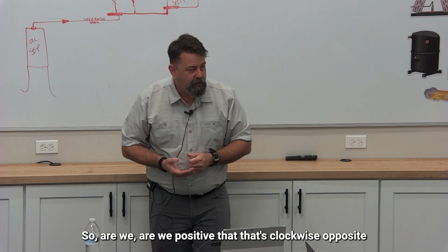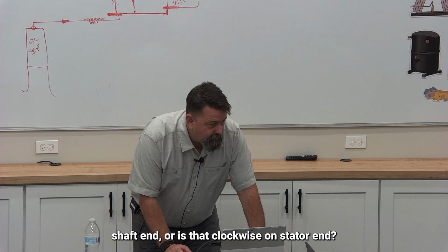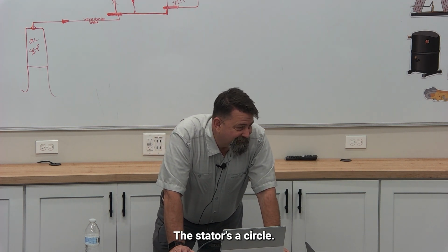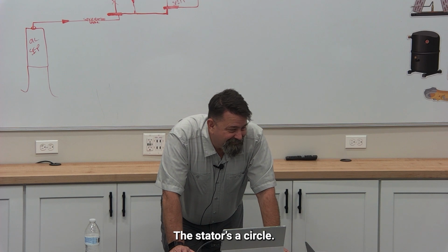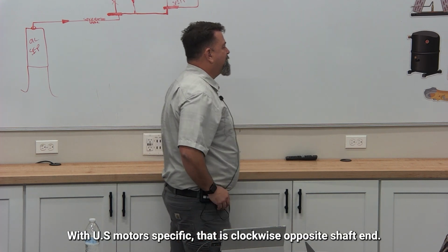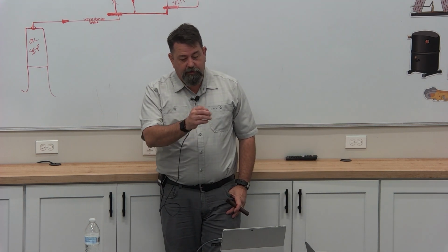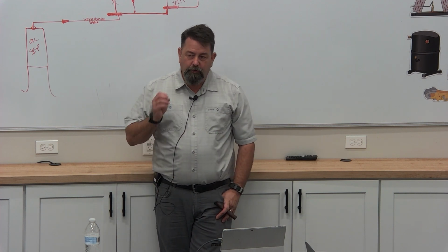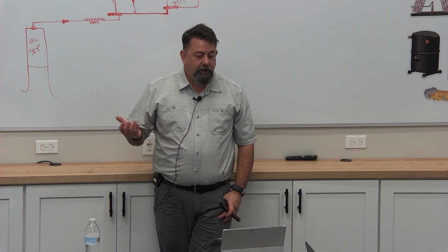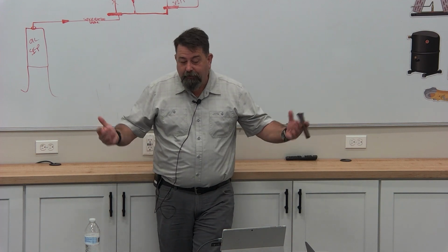Are we positive that that's clockwise, opposite shaft end, or is that clockwise on stator end? It is shaft. The stator's a circle. With US Motors specifically, that is clockwise opposite shaft end. The reason I put this one up here is because US Motors is one of our most common. We use this a great deal. You do need to learn the ones that you're going to carry, what their designation is, so you can keep it straight. There is no standard, and I am sorry for that.